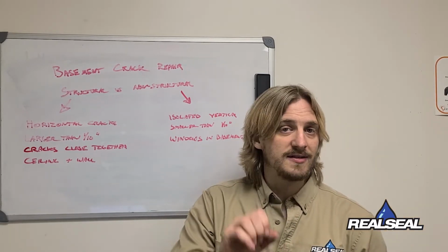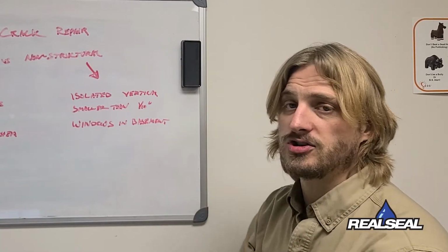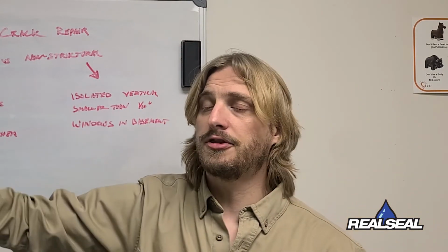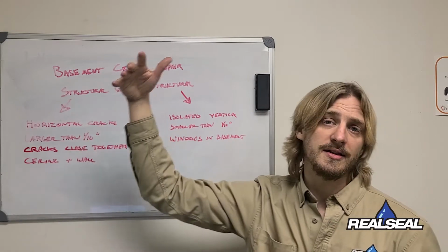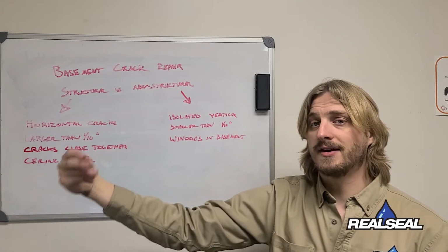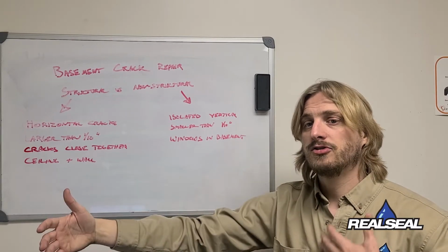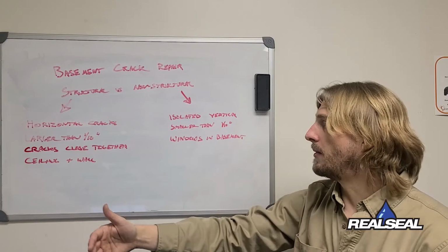The wall plates and C-channels are used by having a plate on the wall or a channel metal beam that goes all the way up the wall and that is connected to a threaded rod at least 13 feet out into your yard, where it then has an end plate and is connected together via bolts that we then screw together and tighten to hold and use the soil outside the home to hold that wall back.